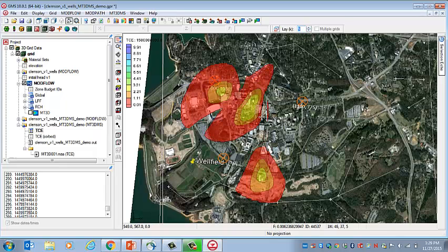So you can see that at Brackett Hall, there's a plume that's going this way and going to discharge to that stream, and another plume that goes this way, and soon it will discharge to this stream. So from a single location, we have the plume spreading in multiple different directions. And this is something that you might actually see out in practice. A lot of industrial facilities are built in uplands near groundwater divides, and they have plumes that emanate from them going in different directions.